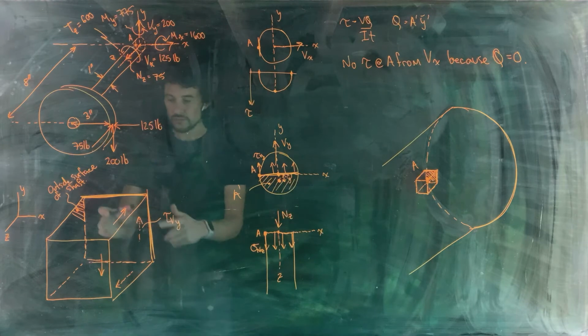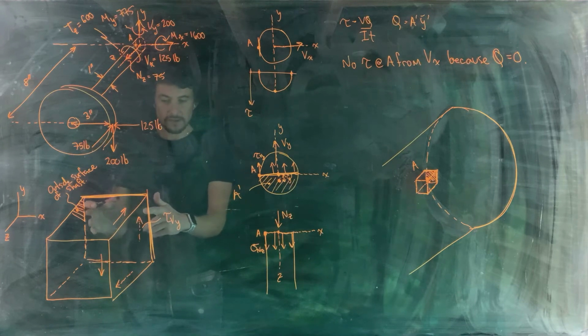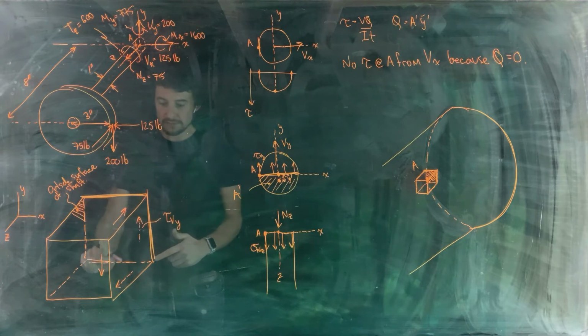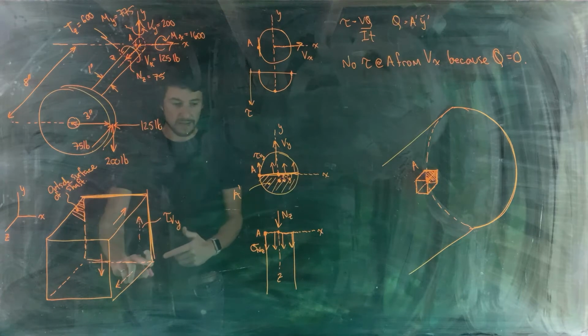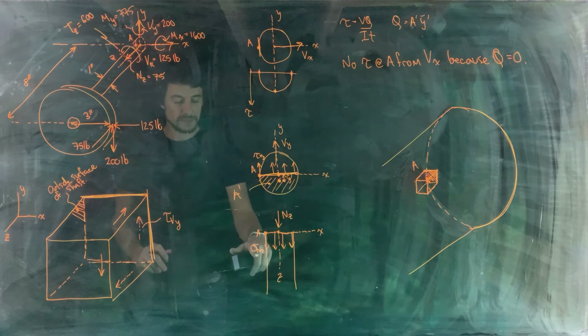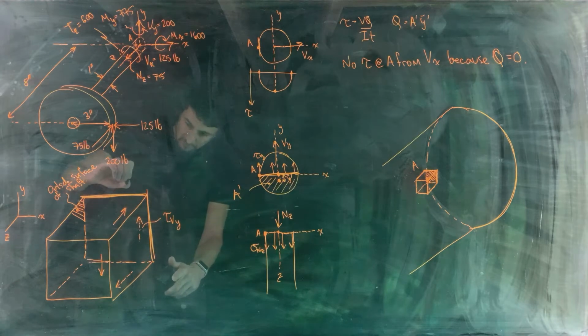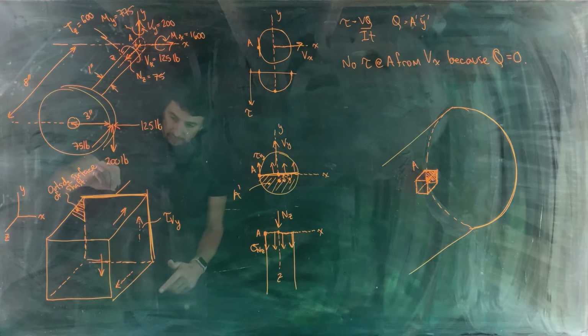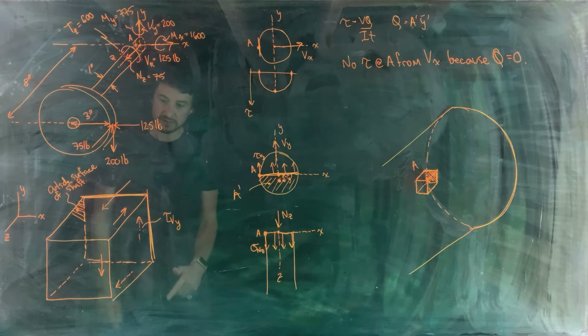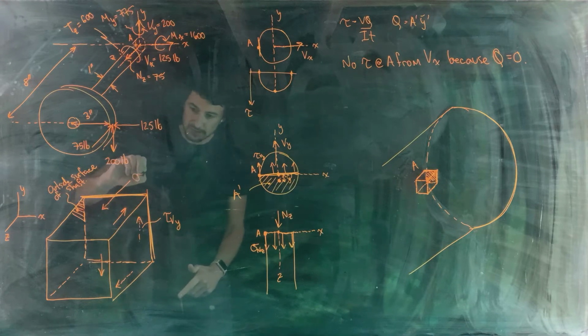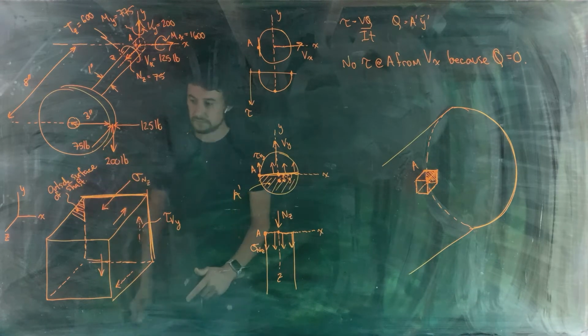So what you want to do is go to your volumetric element, and on the face of the element that's in the section plane, so the back face, just position a compressive normal stress. A compressive normal stress has to be a stress oriented perpendicular to that plane and pushing in on it, like this. Okay, so this is sigma NZ.